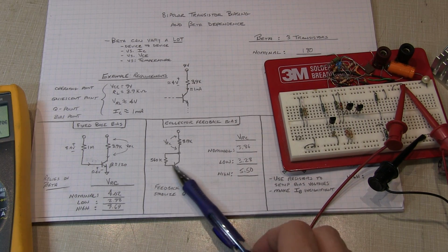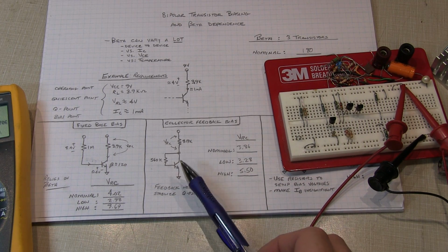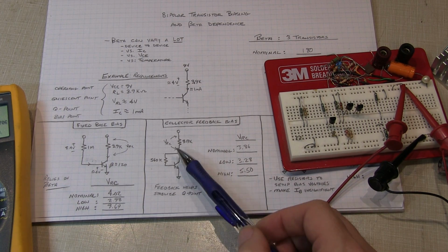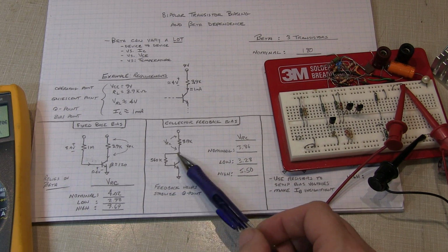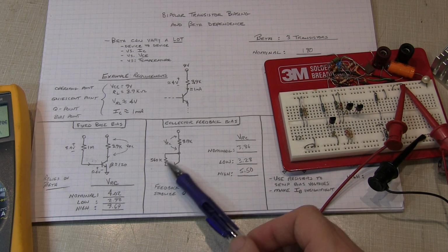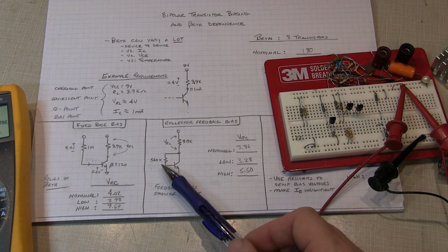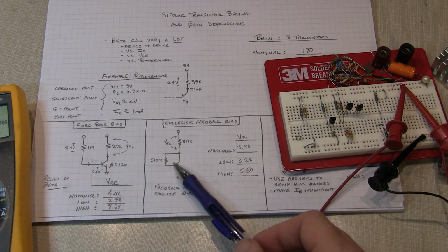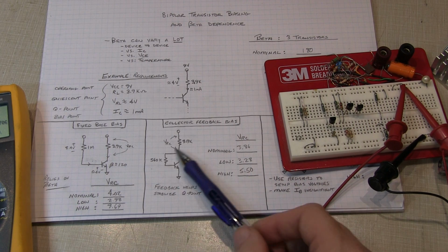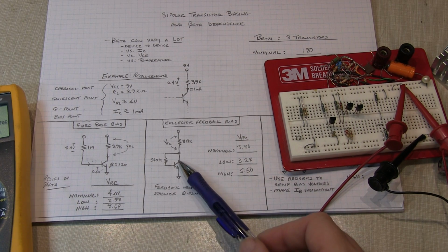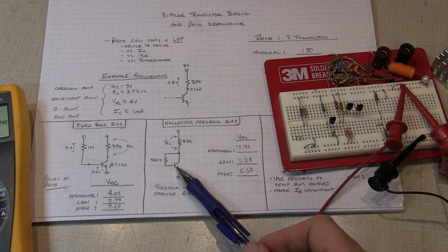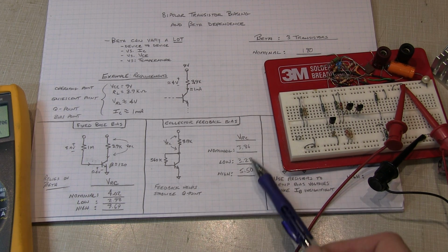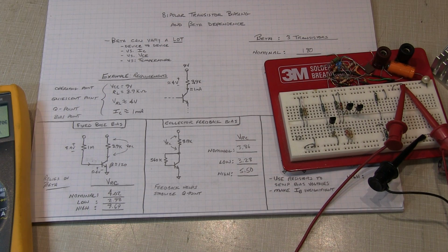Now this is often used, and you see this in many circuits. One downside to this circuit though is that this feedback element that's here is also going to affect the gain. It's basically a feedback element that can sometimes be incorporated into the design of the amplifier, and it'll work just fine. But other times it might be a problem. But this is a very common arrangement for setting up a bias that is reasonably immune to beta. It's certainly not entirely immune to beta, but it's certainly better than a fixed base bias.